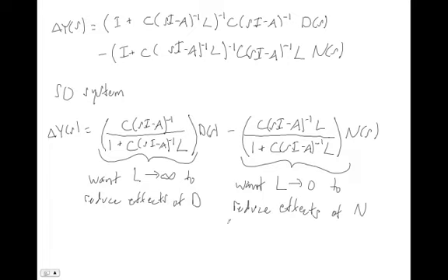So we have these state estimates that look something like, if here's time and here's my estimate of one of my states, I get something rather than looking like this and rejecting it. It may reject disturbances very well, but this is what I actually get out, and that's what I'm passing through to my state feedback. And if you pass that through to your state feedback, you'll also see that in your output. So your system, while it rejects disturbances very well, will sit and jitter around its target value.